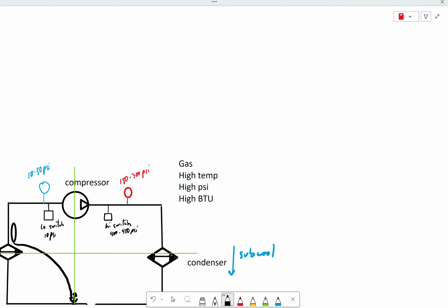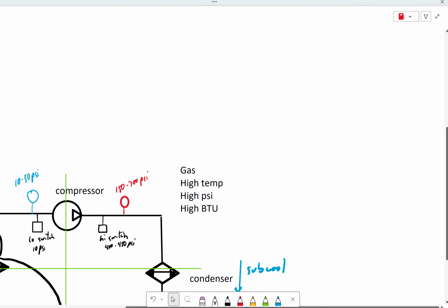So what we'll do first is look at just a simple example. I'm going to draw this quick and dirty and erase it just so you guys can see. For a normal AC gauge set, you'd have a hose with a valve and a gauge, another hose with a valve and a gauge, and then this thing in the middle that gives you your third hose. That's what you have. And you can do most of what you need to do with this set of gauges, I'll be honest with you. But if you want things to be a little bit nicer, take that one, put it right there, and get yourself one of these guys.